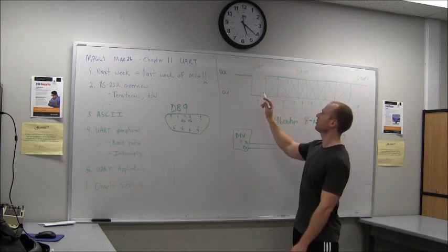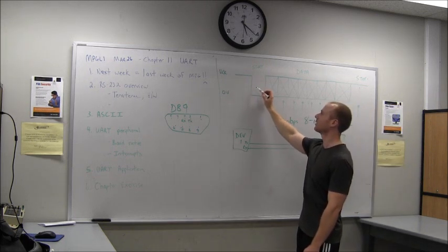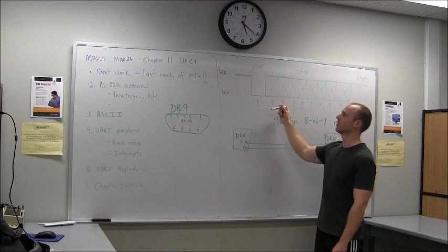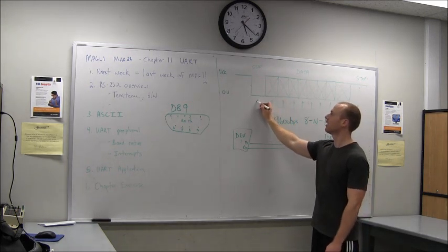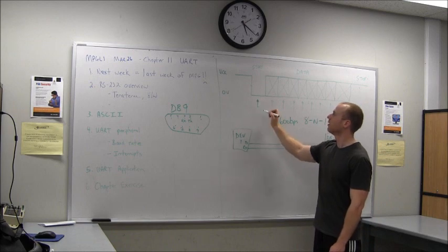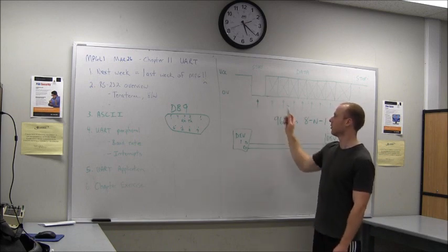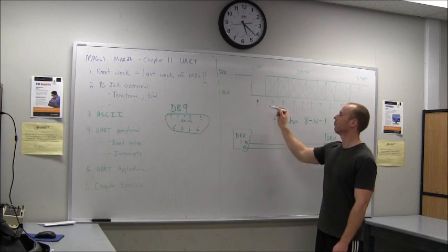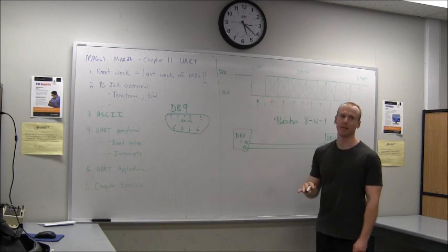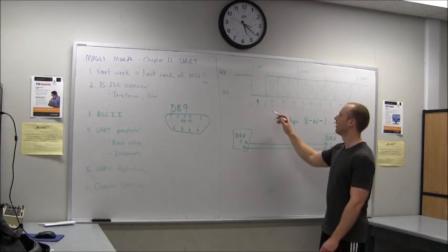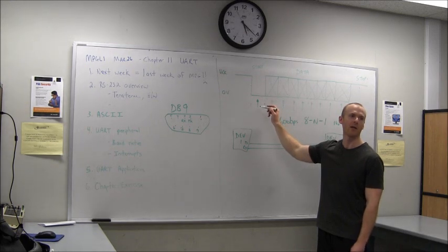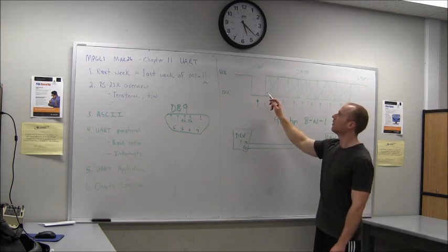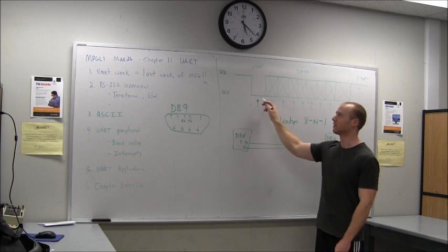As far as this signaling goes, we've already talked about the edge detector, which triggers the listening device to start listening and to start clocking out this data. So the first thing it does is sample: it sees this edge, it knows what rate it's going at, so whatever period that ends up being, it'll know what the halfway point is, and it'll take a sample of the line at the halfway point. So a start bit, as it's called, is a low bit.